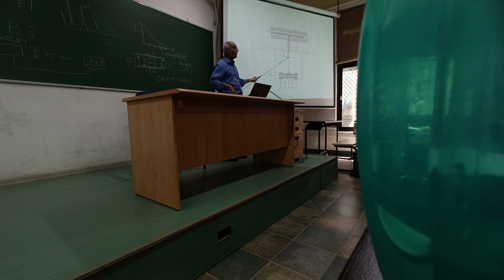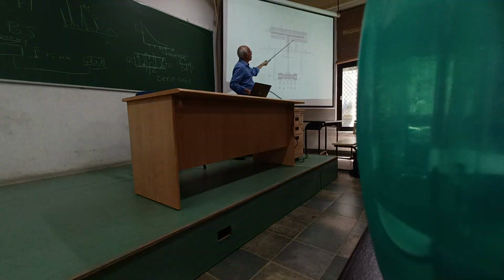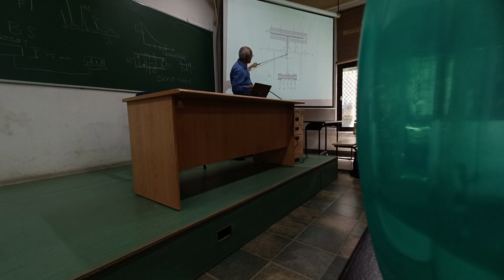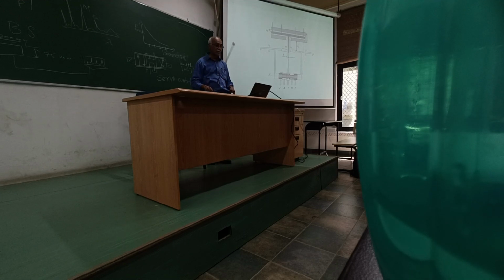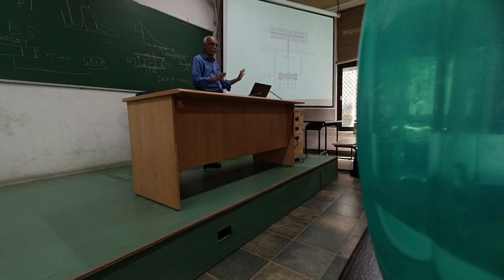So this is the nozzle, flapper, this is the armature, this is a torque motor, and depending upon the current rating, this armature will tilt. Accordingly, this flapper will tilt toward this side or this side. Accordingly, the pressure differential from this liquid will build up, and accordingly the valve position is controlled. This type of valve is known as a proportional controlled valve, or servo control valve in short, which controls fluid proportionally.